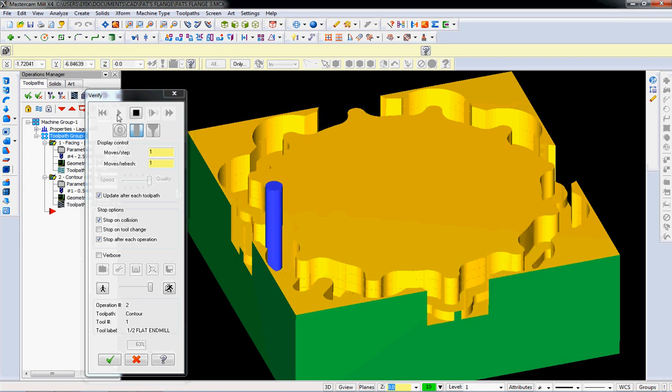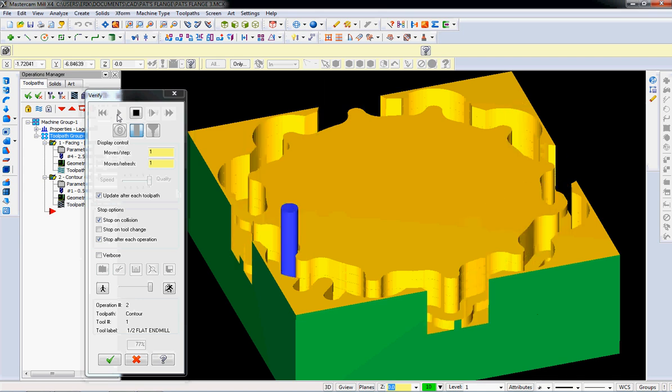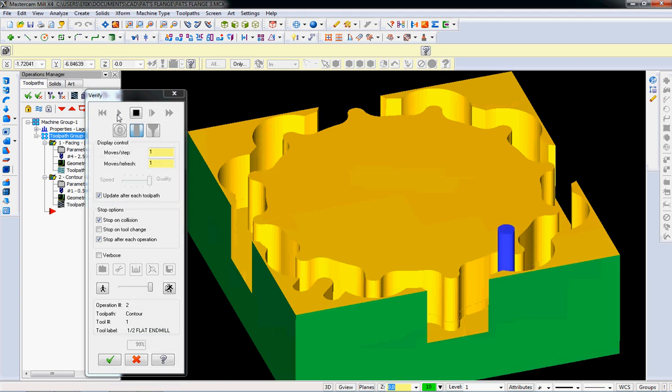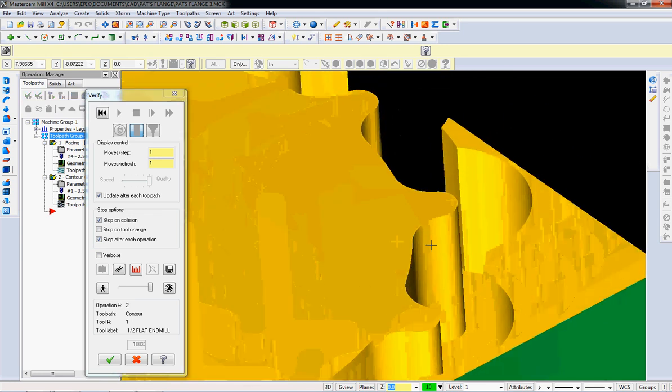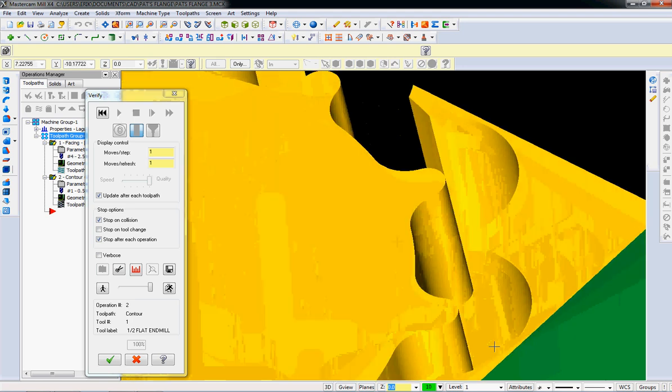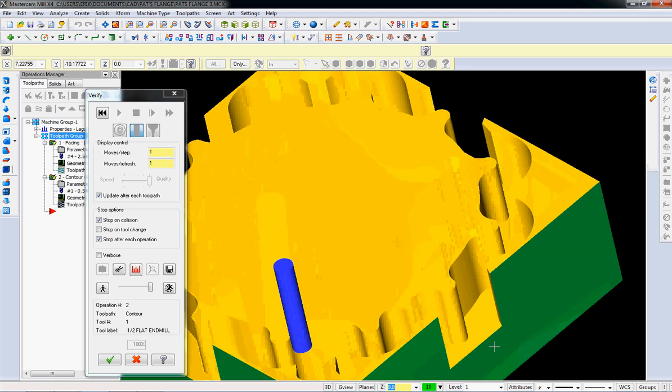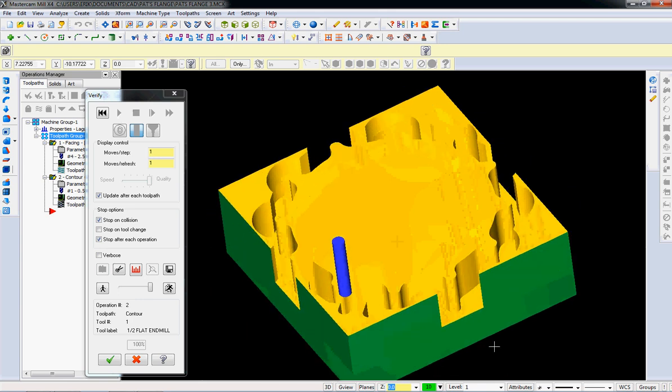And so you can see here, cutting away, outside pass, finish pass, outside, inside, finish, outside, inside, finish. There we go. So notice we have a nice wide path here to get some chip flushing with the coolant. Maybe that's wide enough, maybe not, but those are the extra paths we did there with the lawnmower effect.